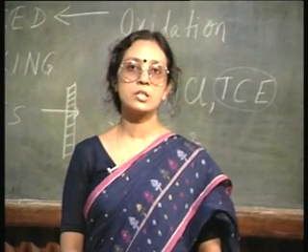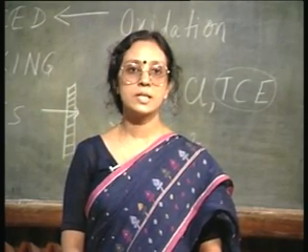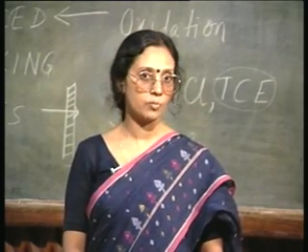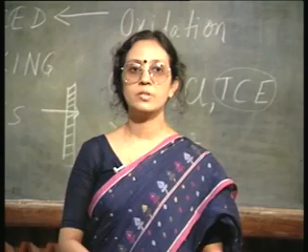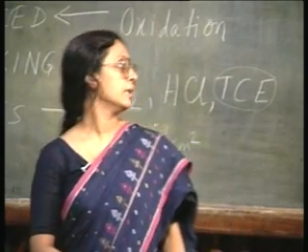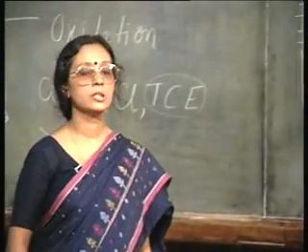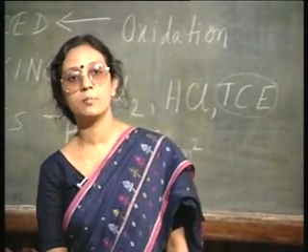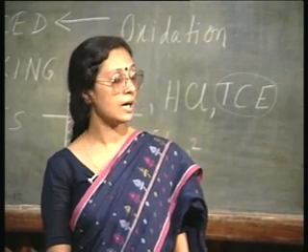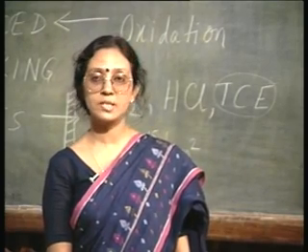As the oxidation goes on, oxygen reacts with silicon, satisfies most of these dangling bonds, and the number of these dangling bonds comes down. But still at the end of the oxidation, there will always be some dangling bonds present at the silicon dioxide interface, and they are the major source of interface trap charge.